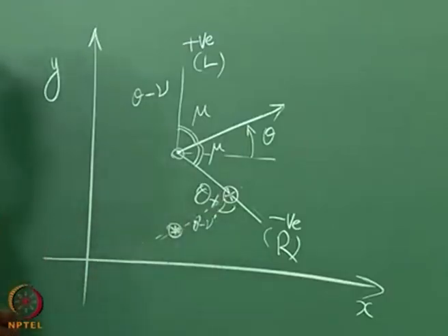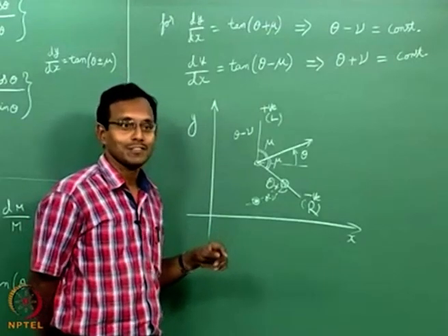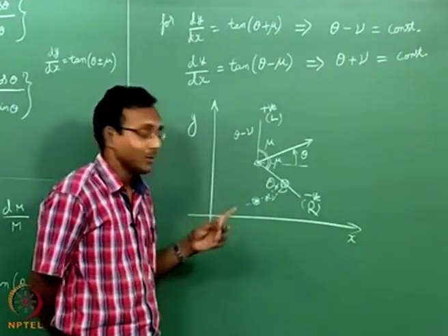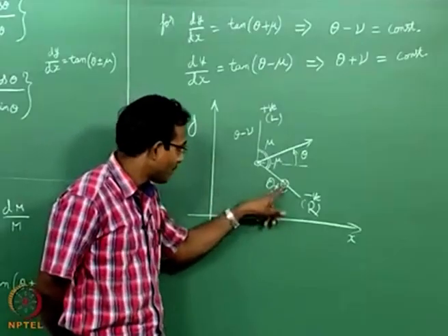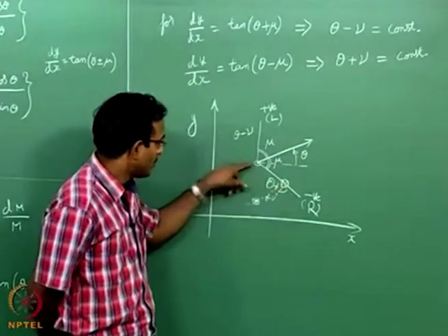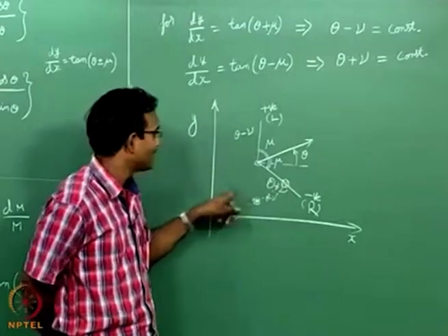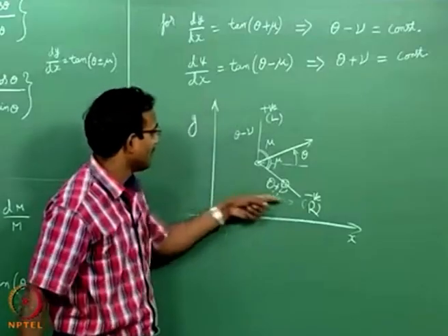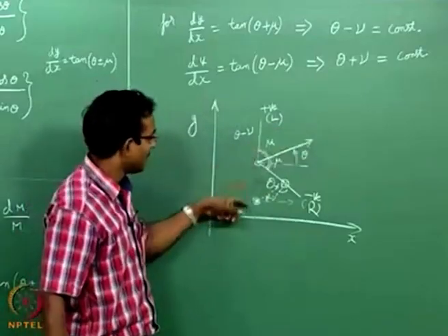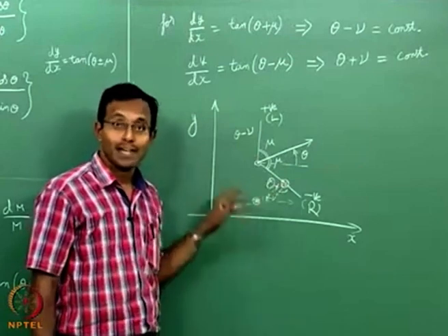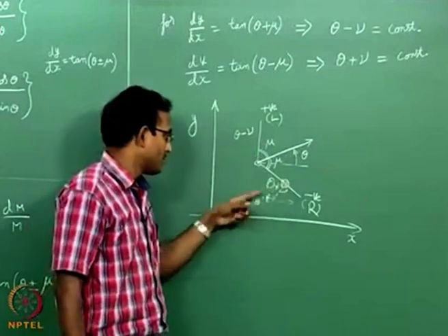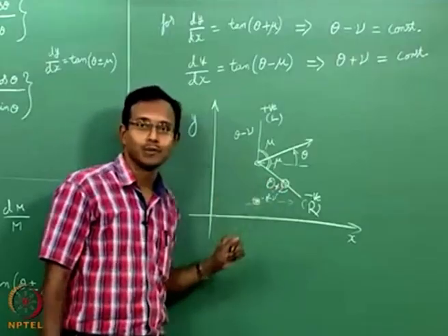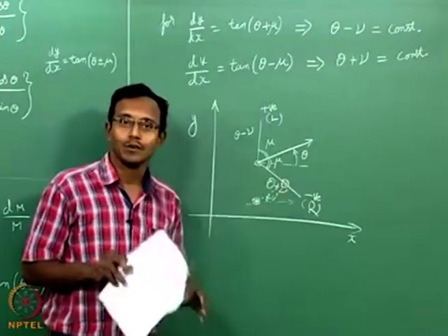Now, we will go back and look at our previous statement which we were waiting for, which is we said supersonic flow depends only on the upstream conditions. Have I used that here? Yes. This point was found from two upstream points. How do I know it is upstream points? We already assumed the velocity vectors to be like this. One velocity vector like this, one velocity vector like this. Based on these 2 points, I got this point. So, I am thinking about upstream points used to calculate the downstream point. That is how I am getting to the new point.